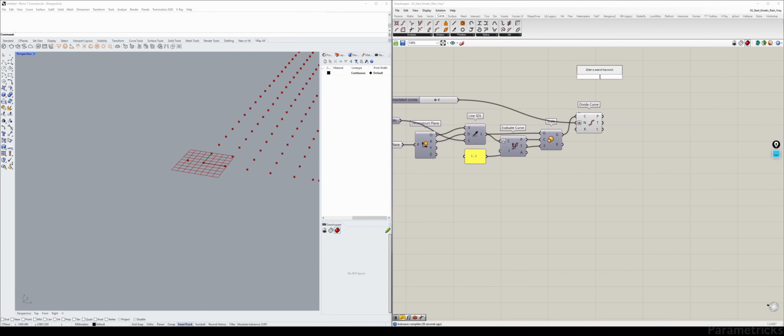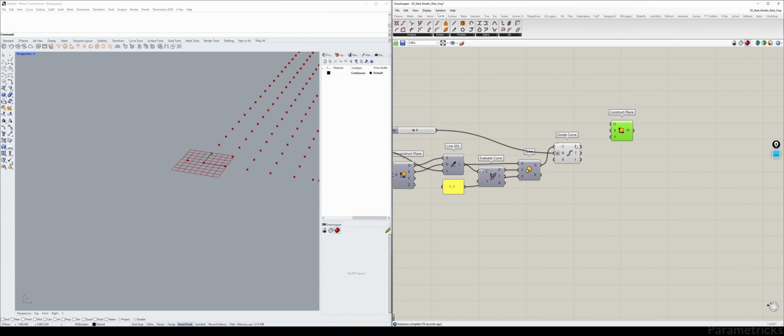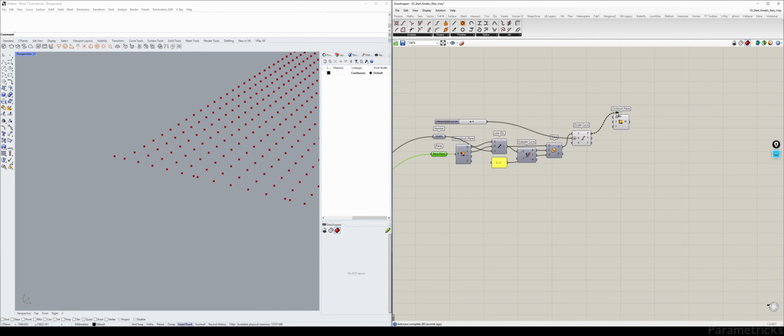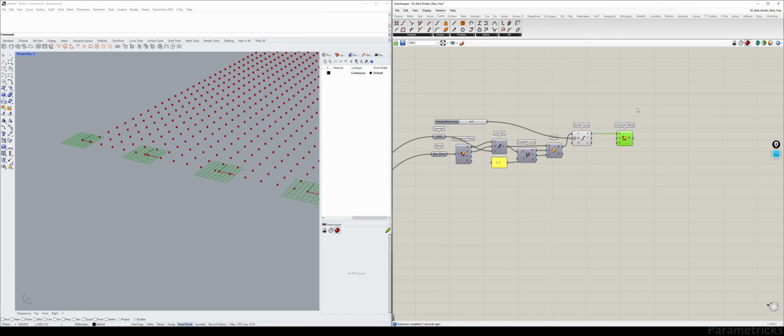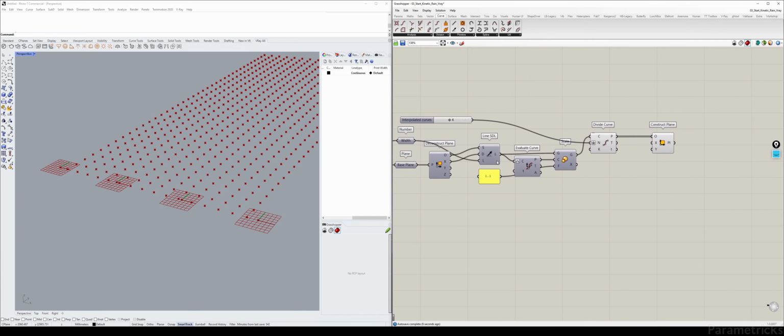One way to do that is we can orient. Well, actually rotate the plane. Let me see if I can find it. Oops. Or actually we can make a new plane, construct plane. Yeah, that should also do. For the origin points, what we're going to do is we will take the division points. So those points. So these need to be orientated. So it takes an x, y, z. We can take one of these. We just need to know which one to take.